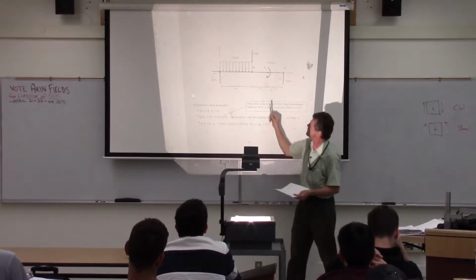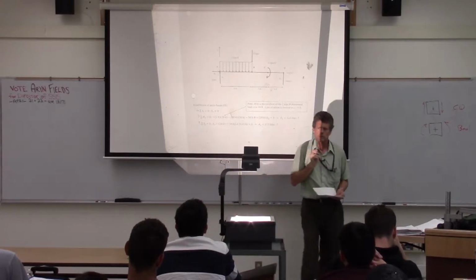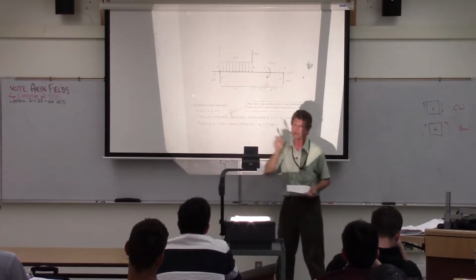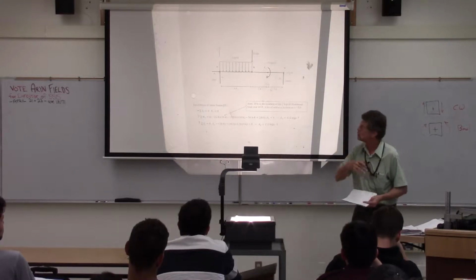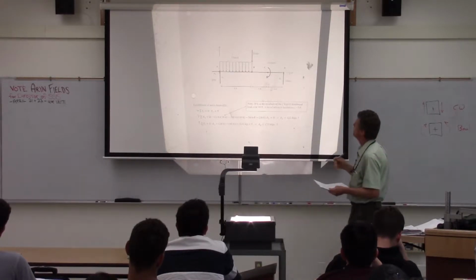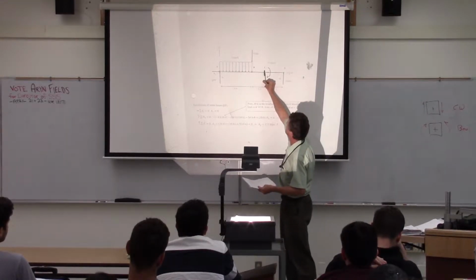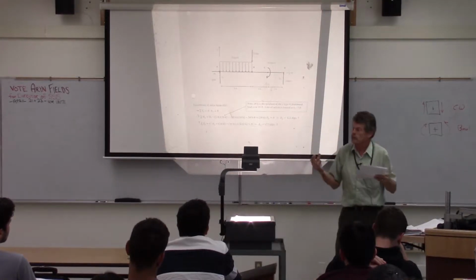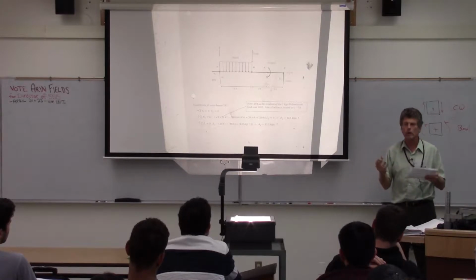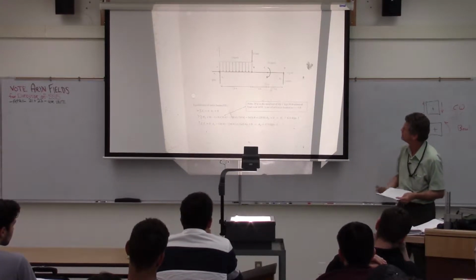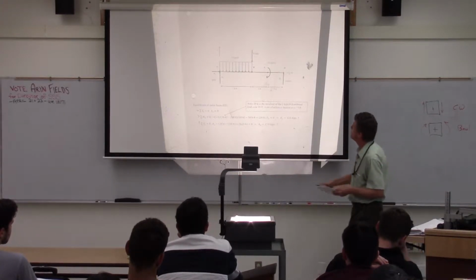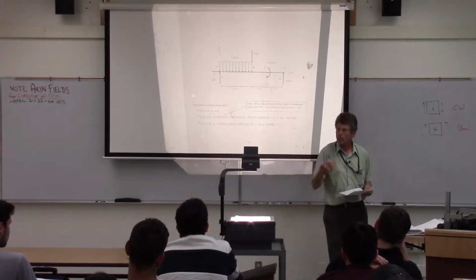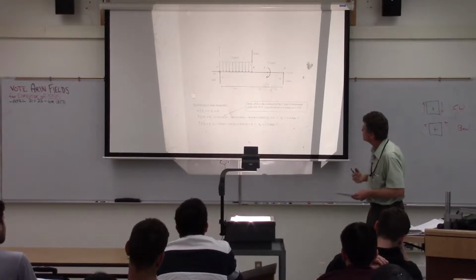We're moving away, but our uniform load disappeared, and we also have this surprise concentrated load of 10 kips. So now all of a sudden it's going to show up. We'll make a cut along here, and then notice when I pass point C, all of a sudden my free body diagram is going to include this concentrated twist of 50 kip-feet. So I'm going to have to make another cut out here and incorporate that particular load into my calculations.